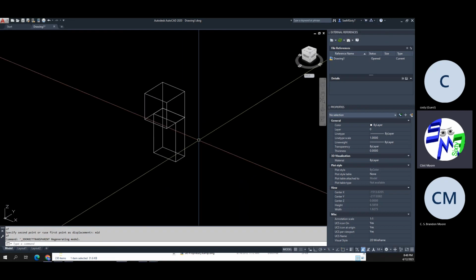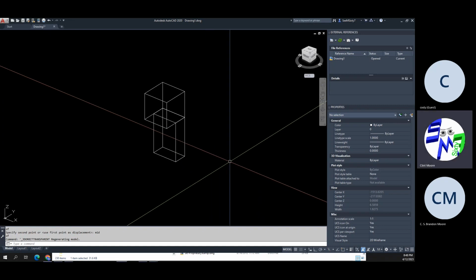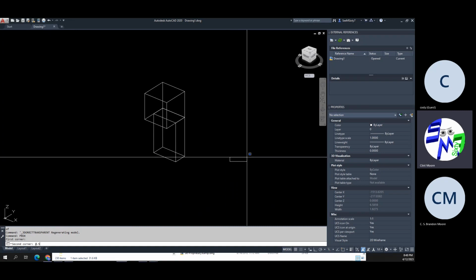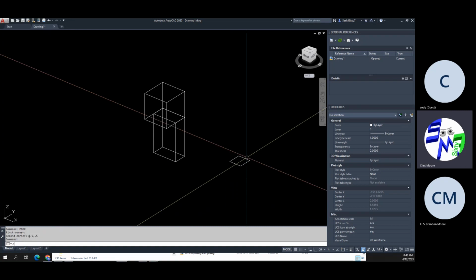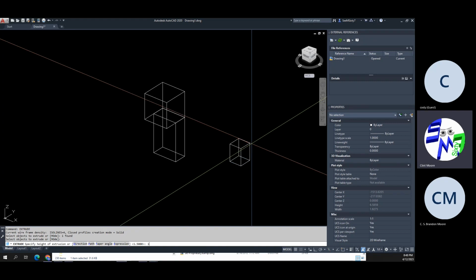Now we need to draw his arms. I'm going to say that's half by half is what it looks like. Okay, PBOX from here. I'm going to say at 0.5 from 0.5 and extrude. That's probably going to be 1.25, 1.25.